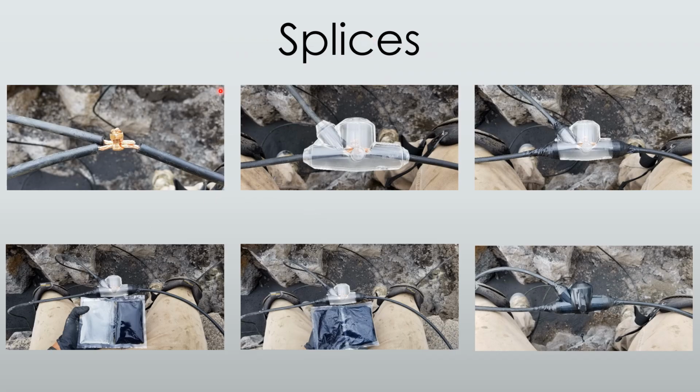It's kind of a little step-by-step on how we do some splices. Little compression kit. I know you can solder them. You can do hammer molds as well if you want to get that really good connection. We've got our plastic kit. These are 3M kits and 90-B1Ns, I believe. You bring some extra electrical tape. The tape they provide in the kits is no good. They do not seal. Take your packet, pop it, mix it, and pour it. It'll set. It'll get hot. You'll have a great splice kit.